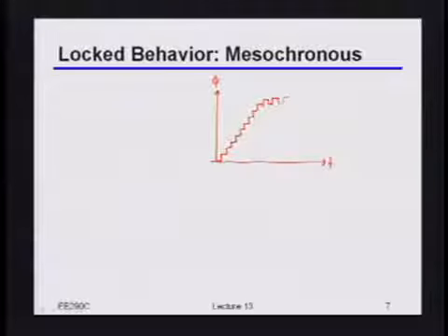supposed to be. And then if things are, let's say, good, and I'll explain what I mean by that in a second, I'm basically just going to dither right around whatever that phase position is supposed to be, right? So let's say somewhere around here is nominally where the phase is supposed to be. Then ideally speaking, that's the point that I would be dithering around, okay? And it may not be exactly 50% like this. If there's some noise or something, then it may actually have different code densities. But bottom line, it should be dithering around this point here. Okay?